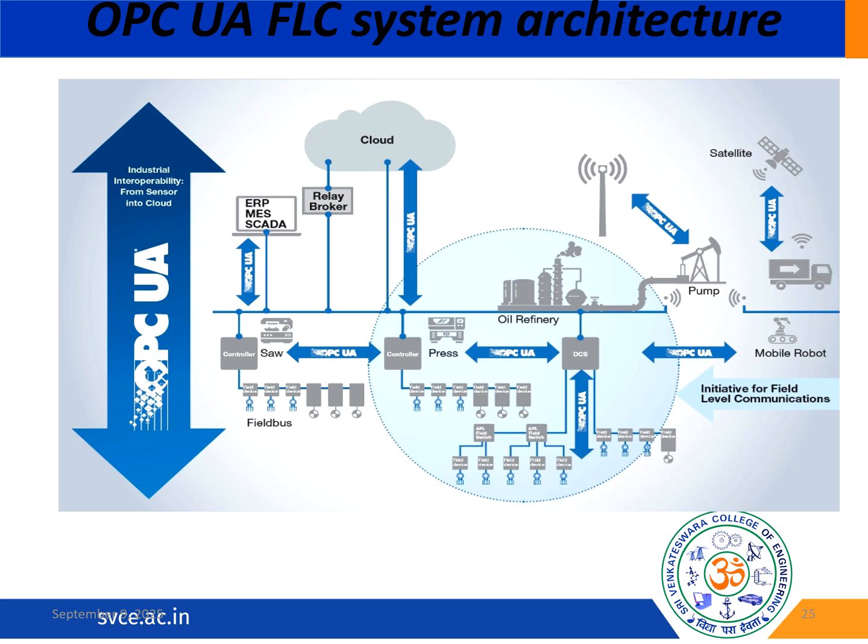So top right, if you see, we can have some cloud and remote systems. The cloud is represented with OPC UA securely, which transfers plant data into cloud applications, mainly for performing analytics, AI, and optimization. And here you have a relay broker. The relay broker acts as a communication hub between the cloud and the enterprise system.